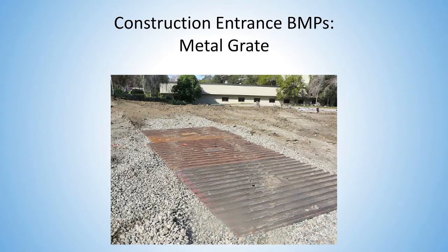Metal grates, cattle grates, in this case called a rattle trap, have different purposes. Some of them actually shake the tires and cause sediment to drop in between the metal fabric. In this case, I actually bumped into the guy that developed this device in California. It's designed to flex the tires, so it doesn't shake the vehicles as much. It flexes the tires and causes sediment to drop out. Usually these are assembled in a group of 3: an entrance, a middle, and an exit.